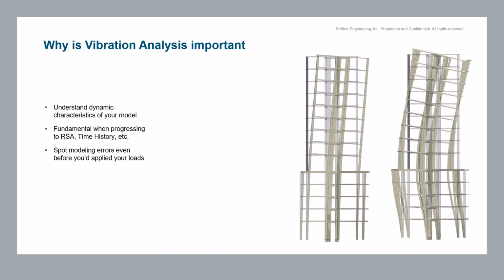Another aspect of this is that you can run vibration analysis, specifically unstressed vibration analysis, early on in your modeling process before you've even applied your loads. So it helps you spot modeling errors that could occur while you're still fairly early and in the malleable stages of your modeling process. And we'll look at, in the next couple of slides, some examples of where that can be spotted.